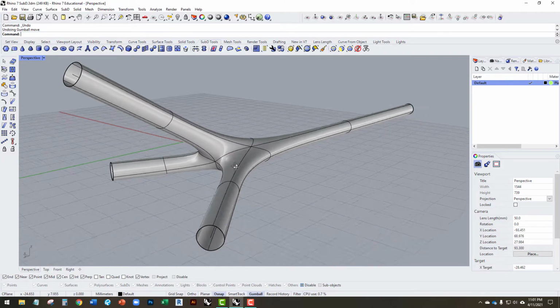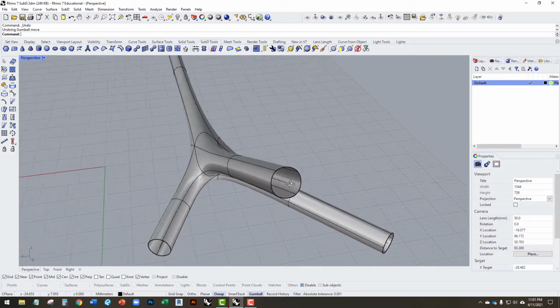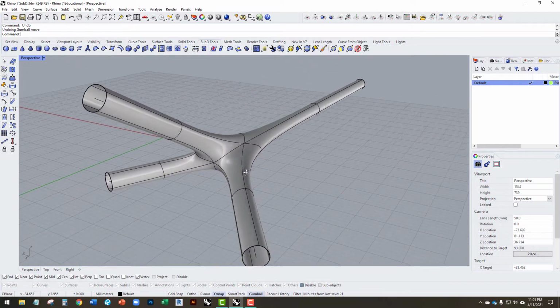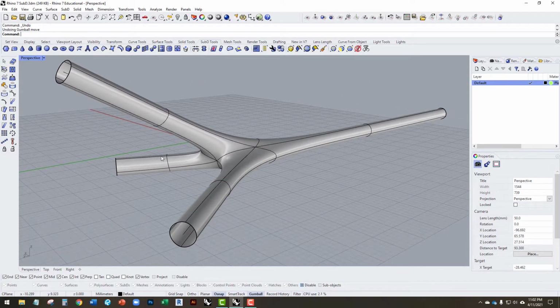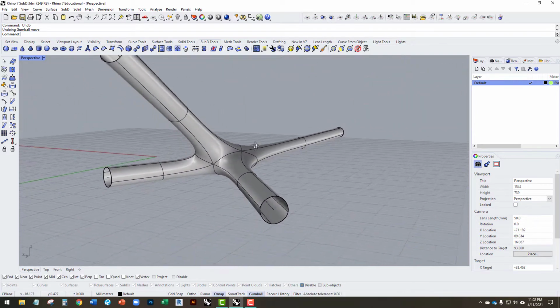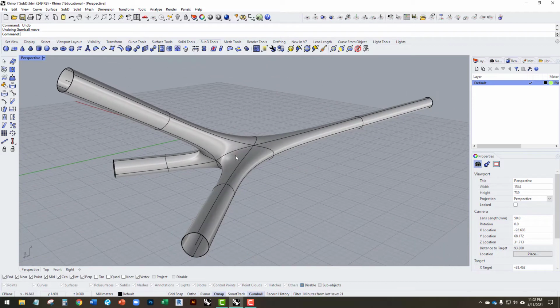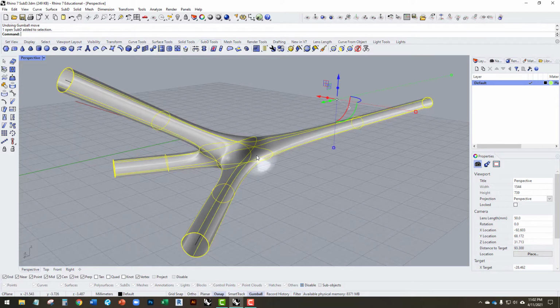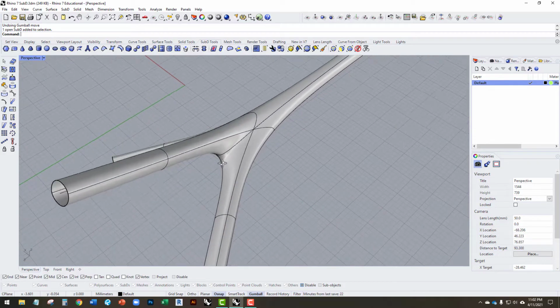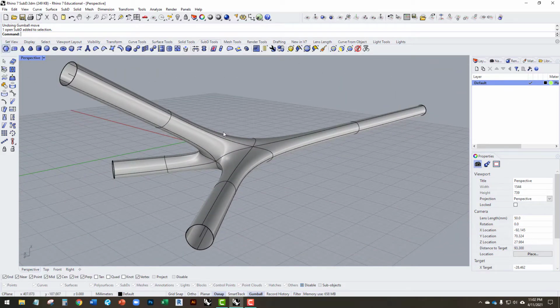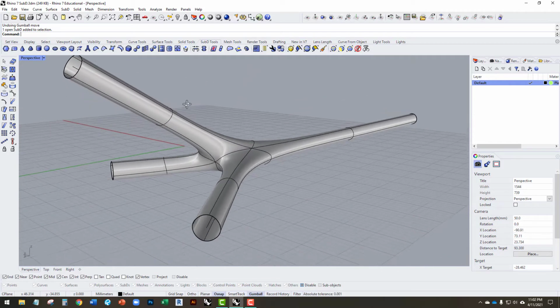This tutorial is going to cover an interesting geometry type in Rhino. This is Rhino 7, and in addition to surfaces and poly surfaces and meshes, there's another type of geometry called subdivision surfaces, or SubD surfaces. This type of geometry is useful for modeling smooth geometry and complex curvature relatively easily. It's like modeling in clay versus solid geometry. So I'll go over the basics of this and cover some primitives and how it can be used and how it can aid in any workflow.